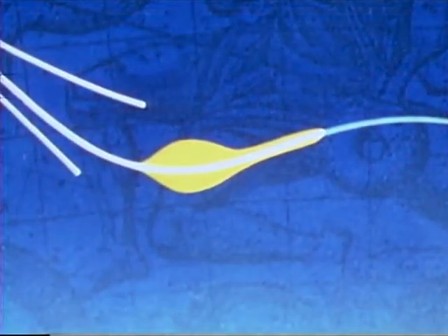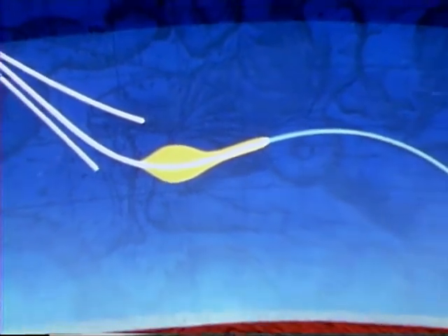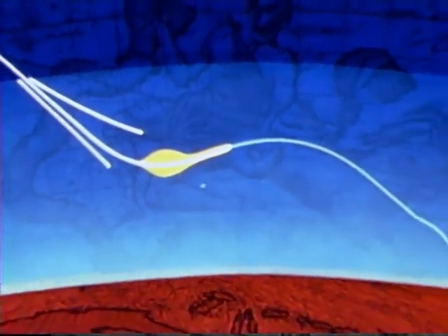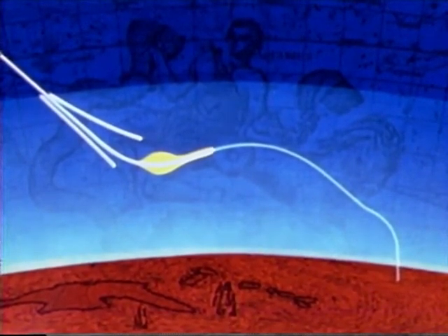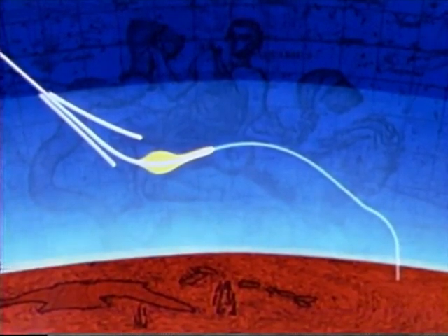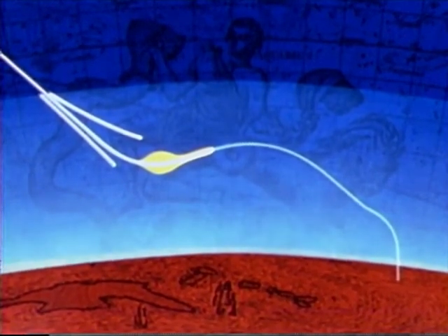During the remainder of the first control period until the skip, the landing footprint will be reduced to this area, about 690 miles long. Only minor adjustments of the trajectory can be made as the skip is approached. If all goes well during the first control period, the spacecraft and crew should be on a trajectory that can be safely controlled during the second entry. We are now ready to look at the skip and the final part of the entry phase.